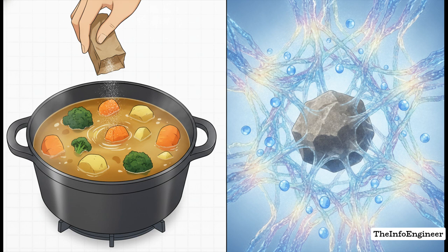They're essentially long-chain polysaccharides. When the concrete is just sitting there at rest, these chains intertwine to create a viscous gel that traps the water and suspends the rock. But here's the brilliant part. When you apply shear force, like when you pump it or vibrate it, those chains straighten right out and the concrete flows beautifully. It's called shear thinning behavior, and it is a total lifesaver on site.